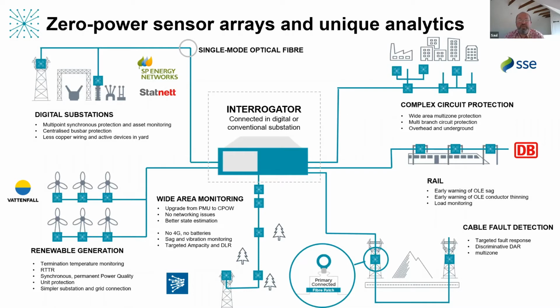But generally speaking, we're very well suited to wide area monitoring because we're able to offer things like continuous point on wave interrogation and data sampling from a lot more locations without the need to backhaul that data through some kind of switched IP data network. We're avoiding a lot of the traditional architecture involved in IP switch networking, PDCs and data concentrator stages to get data back centrally to make better decisions.